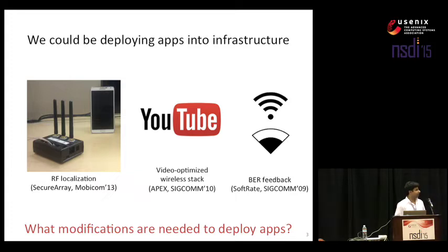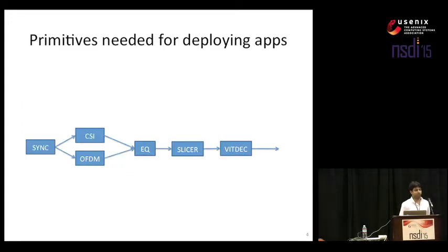So let's start out by looking at a typical signal processing chain that these base stations would be running. It would typically consist of some kind of a data flow graph to describe the signal processing, which is a flow graph assembled using signal processing blocks. So what I show here is an example based out of a Wi-Fi chain, and LTE looks very similar, which includes some kind of synchronization, channel estimation, and bit decoding.